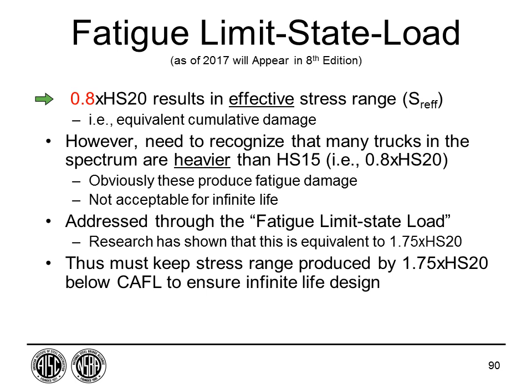But there's also something very important here. This is the truck that creates the same effective fatigue damage. This is all trucks combined. Now, when I make that statement, we also have to recognize that means there's going to be a lot of trucks that are much heavier than 0.8 times the HS20, or almost the HS15. We know that. How do we address that? Well, we address that through what we call the fatigue limit state load. That's shown that the upper bound vehicle is the HS20.